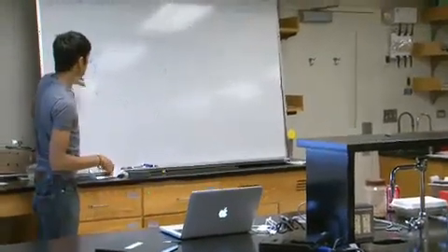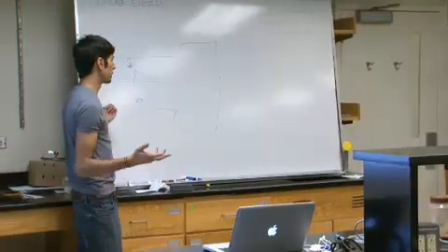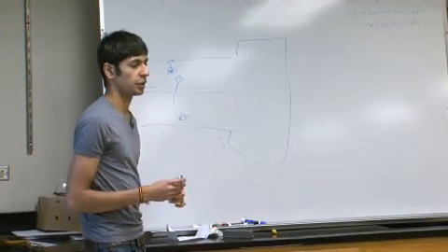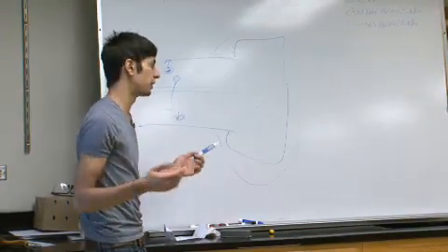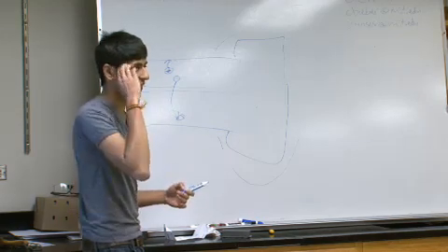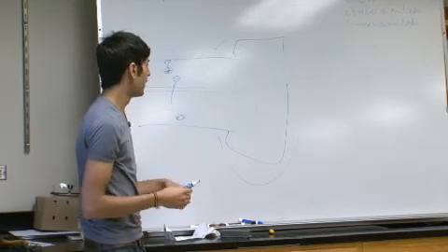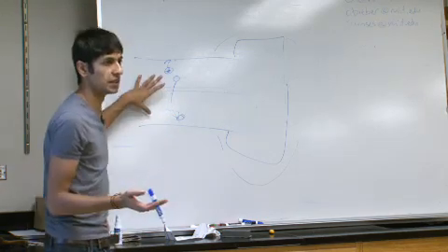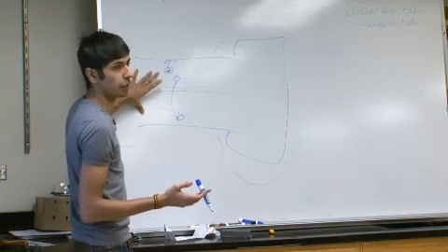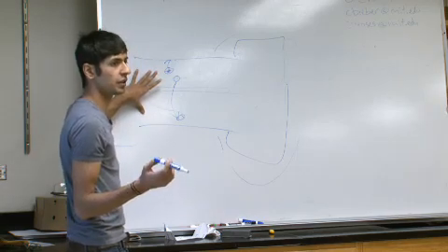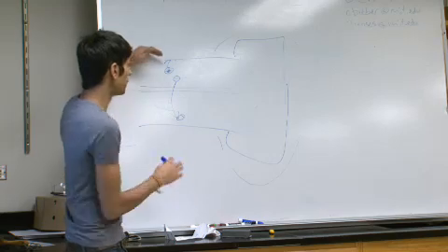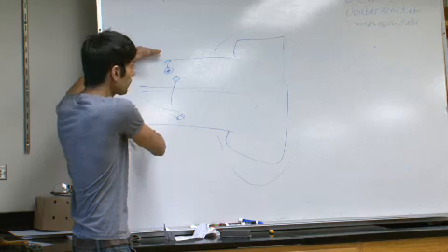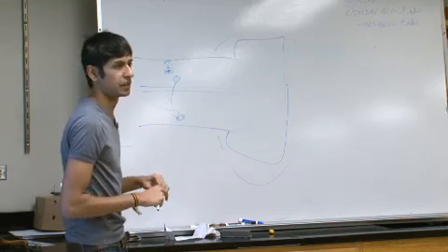So the absorption coefficient of silicon is really low. You have a lot of different solar cells, right? You have amorphous silicon, multi-crystalline silicon, and thin film cells as well. But the reason why silicon cells are so thick is because the absorption coefficient is so low that you need a thicker area to be able to absorb most of the light. I'm not answering your question, am I?